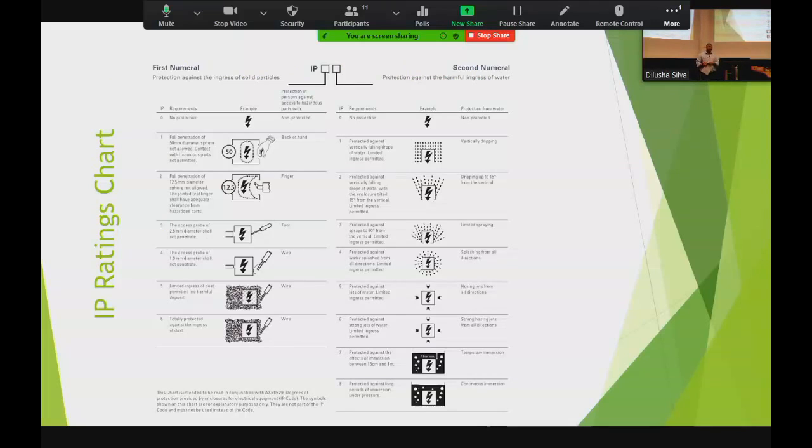I just thought I'd throw this into it as well. IP ratings. Two digits. The first digit is a solid, which tells me it's the old finger test. Can I prod my finger through the wire mesh and electrocute myself? So the first digit is a solid mass. The second one refers to ingress of water, can also be gas. So a non-solid. All right?